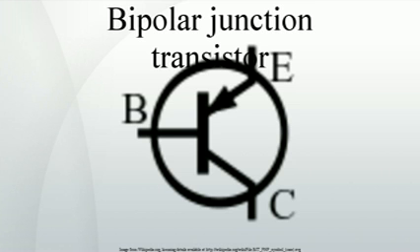Active mode NPN transistors in circuits. The diagram shows a schematic representation of an NPN transistor connected to two voltage sources. To make the transistor conduct appreciable current, on the order of 1 mA, from C to E, VBE must be above a minimum value sometimes referred to as the cut-in voltage. The cut-in voltage is usually about 650 mV for silicon BJTs at room temperature but can be different depending on the type of transistor and its biasing.